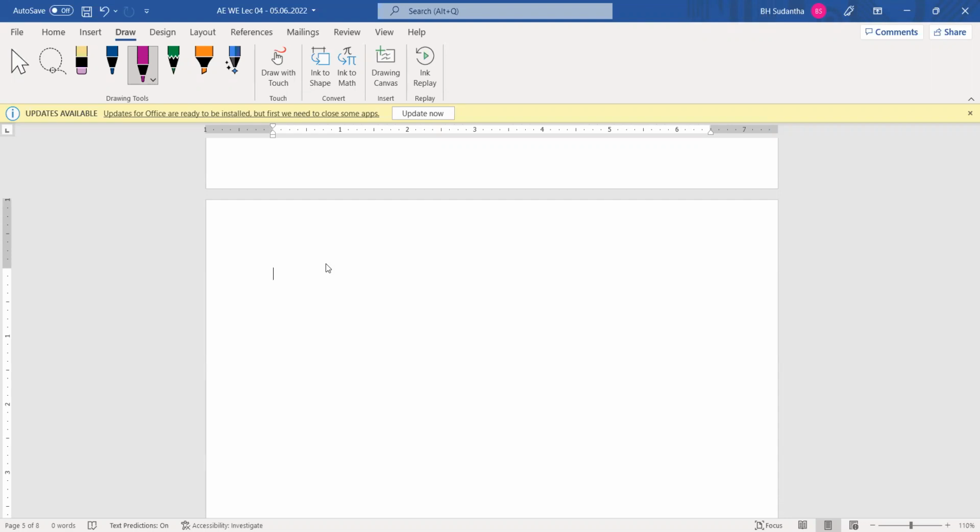Then, in addition to that voltage regulation application, we can use these Zener diodes for voltage clipping. Again, it's a very simple circuit, the voltage clipper circuit. And we can use these voltage clipping circuits for various applications. When you want to clip your voltage at a particular point, you have to carefully select the Zener diode voltage, considering your clipping voltage value. So all the time, the Zener voltage plus 0.7 volts will be the clipping voltage.